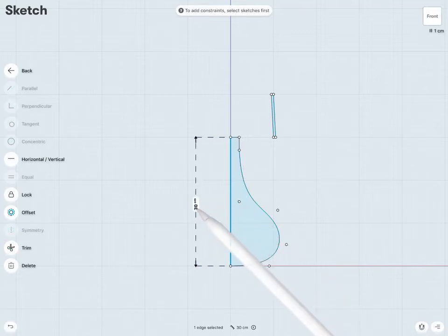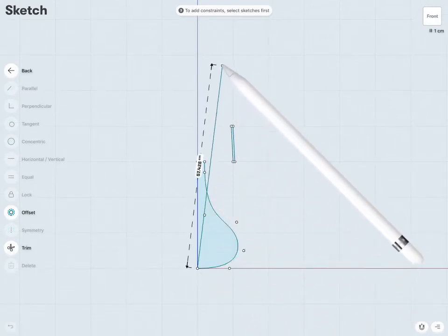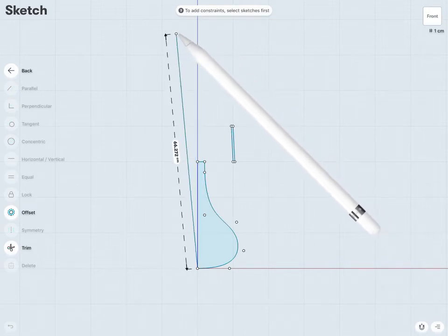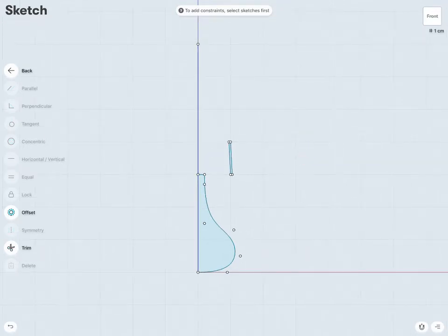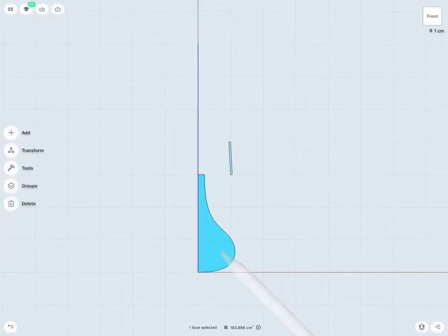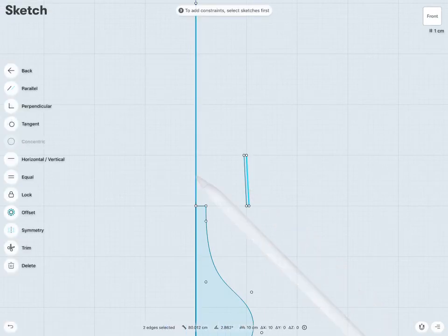I could actually use an existing line, I could use this line itself. But just for illustration purposes, I'm going to draw in an additional line, maybe right about here. And I want that line to be going just straight up in this case, about that z-axis. So this larger line here, going straight up about my up or z-axis, is what I'll be using as my axis of revolution. And I'm going to revolve both the base about that line, as well as the lampshade about that line as well.